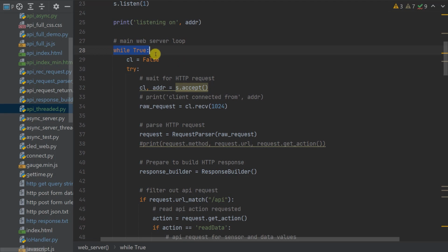and then we go into our web server loop where we're just doing a forever loop where we're going to wait for an HTTP connection, and again we're using that blocking method here. So our code and this particular core will halt at this point waiting for our HTTP connection. But of course that doesn't matter because our control code is running at full speed on the other core.